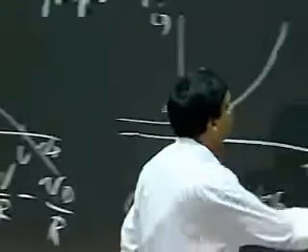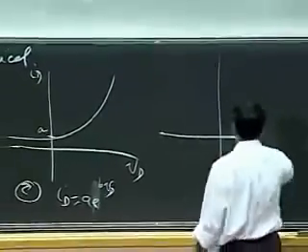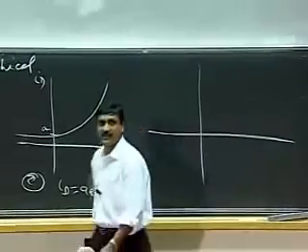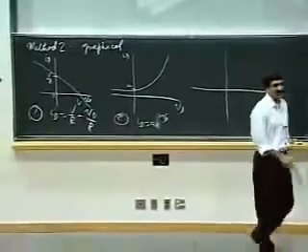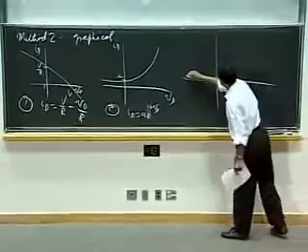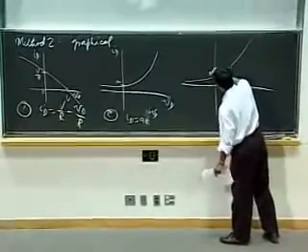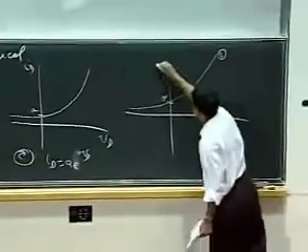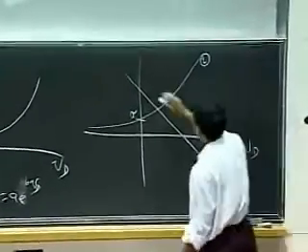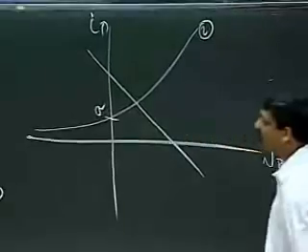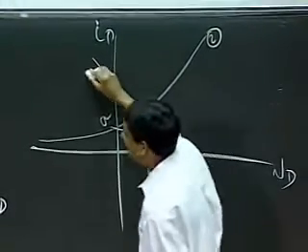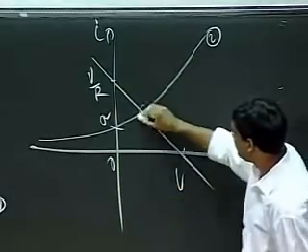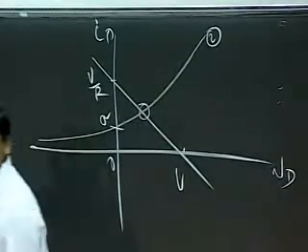So what I can do is simply solve these by superimposing the two curves on the same VD ID template here and finding the intersection of the curves. I can take this curve corresponding to 2, and I can take this curve corresponding to 1, and this is V divided by R, and this is V, 0, and I can find the intersection point.